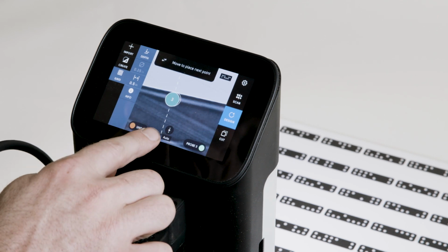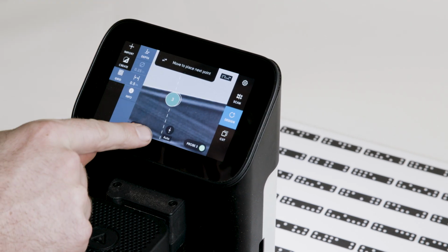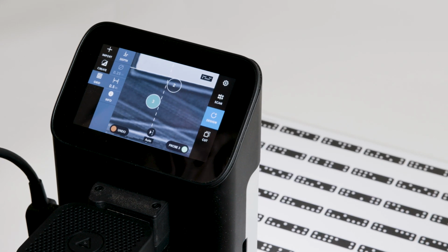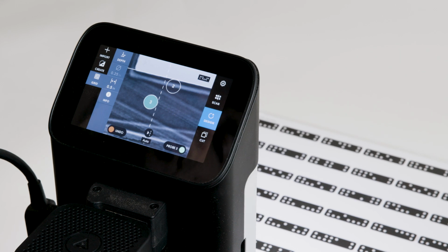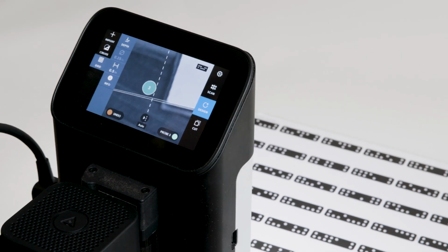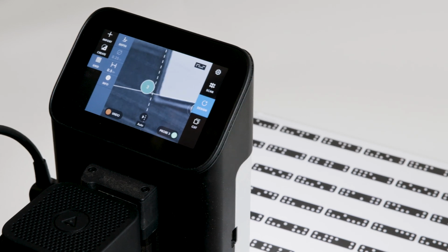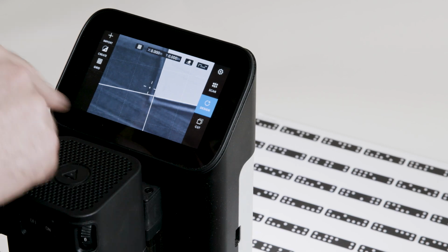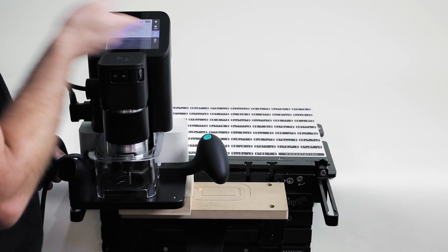And you'll notice this is auto. It's currently using the center. We'll get to that later. But as I round that second point, you'll notice it swaps automatically to the right-hand side of my probe. That's because it's anticipating we're going to come through here and do a standard probe against this edge. So I'm just going to touch it there and probe again. So now you'll see we have a grid perfectly aligned to our stock.